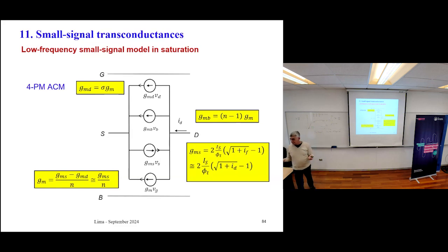The variation of the current will be the same if you change source or drain by the same amount. The difference is that if you increase the source, the current decreases, and if you increase the drain, the current increases, since the conventional current is from drain to source. But if the source increases with respect to the drain, the current reduces or changes sign.